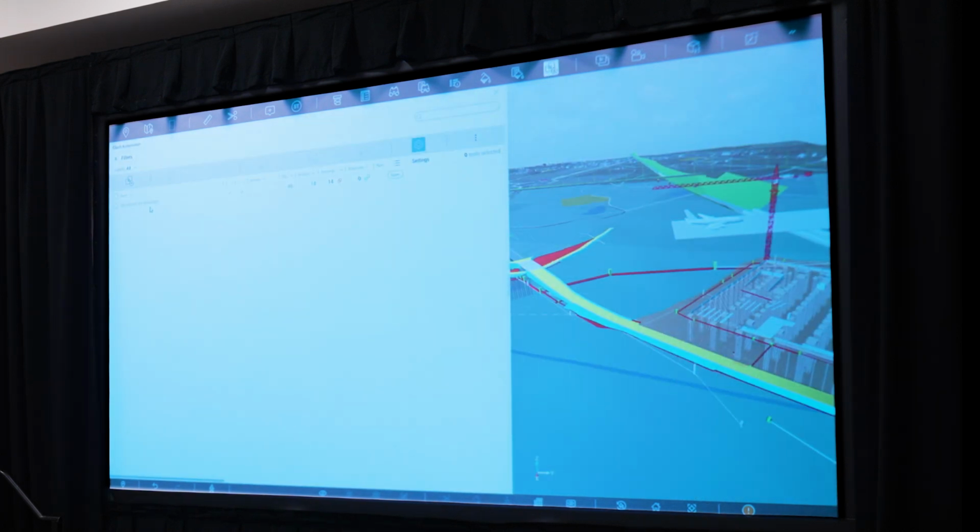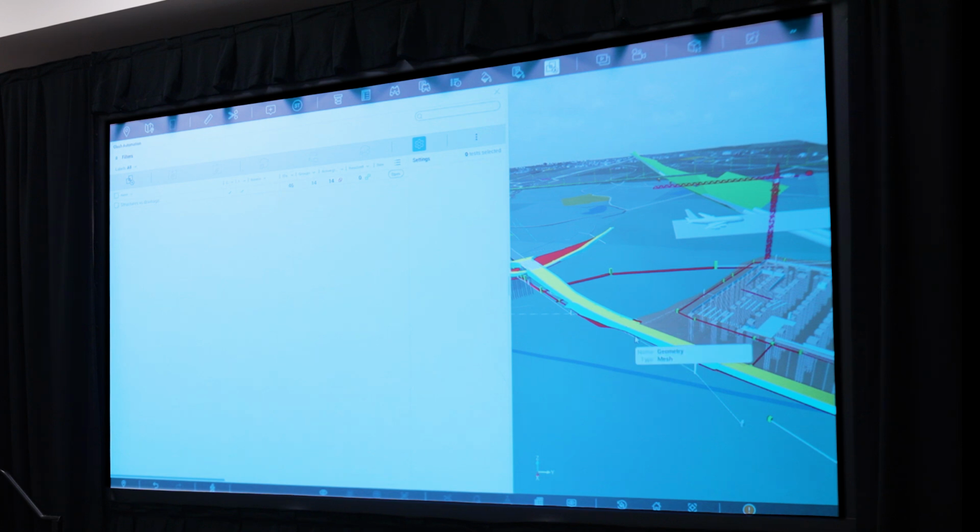So it's a very, very simple clash test. And even though I've banged on about the best way or the correct way to set up your search sets, it's just because of the data that's in here, it's that terrible. I've had to fudge stuff and try and make things work, but that's just because of the information I've got to hand.